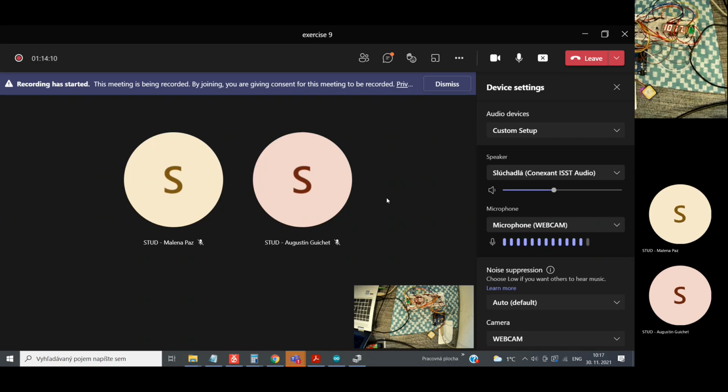When you receive a complete sentence, including A, it's a valid sentence. Then you synchronize the clock, hours, minutes, seconds, and then you could turn off the GPS receiver. Because it's not very important to have, for example, 0.2 second accuracy for the clock.